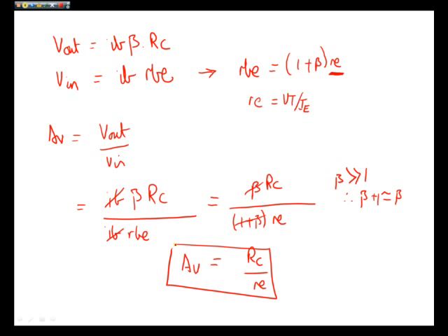We have now calculated exactly what we set out to for this particular design, and we've worked out our equations. One thing just to tidy up here, we should note that our current flow is inverse, so it's a negative term here. Therefore, we should have a negative sign all the way along, because our output is minus RC over RE.